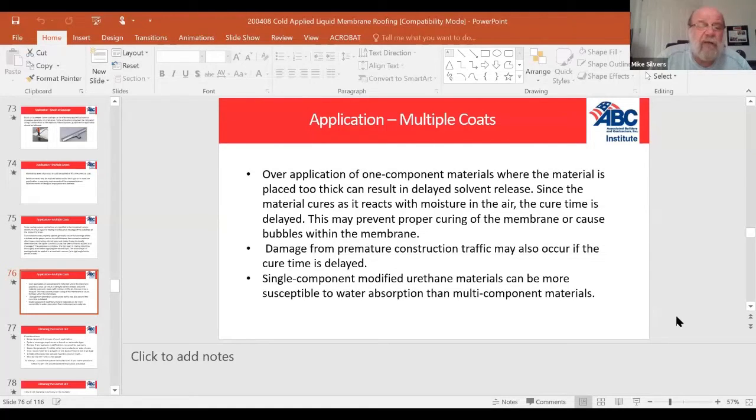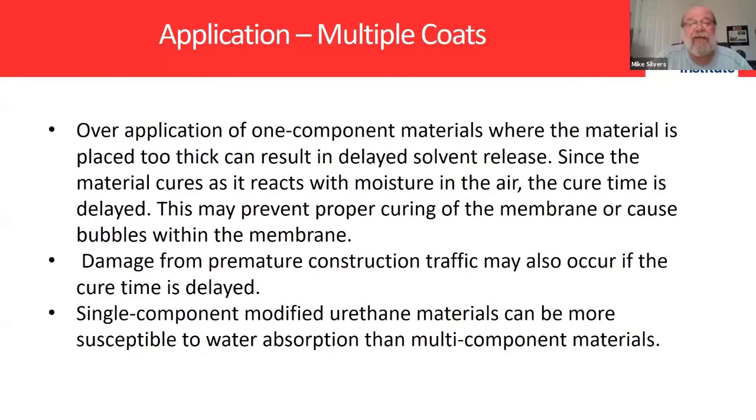If I can, Glenn mentioned that when concrete cures, it's a chemical reaction, and the only time, particularly in Florida, you'll get typically your best cure in the summertime is right after that chemical process has stopped, because it's so high in the air here that once that stops, it more often than not starts absorbing some moisture, not losing moisture. Take a day like today: if this gets to that concrete and it gets wet all day long, you've lost that ability to get that chemical cure. And so it will take a long time in Florida for that roof to dry out.